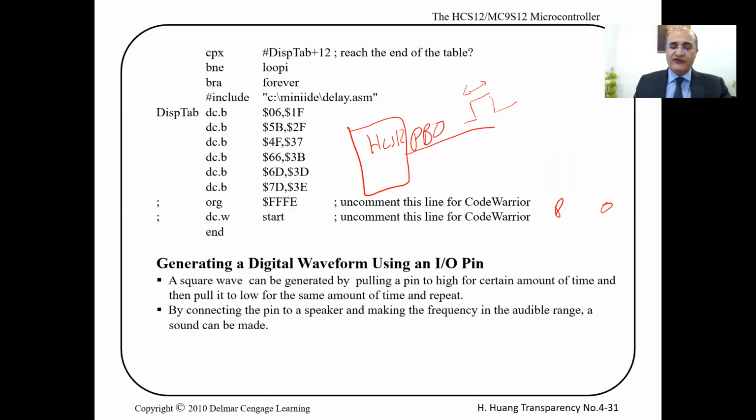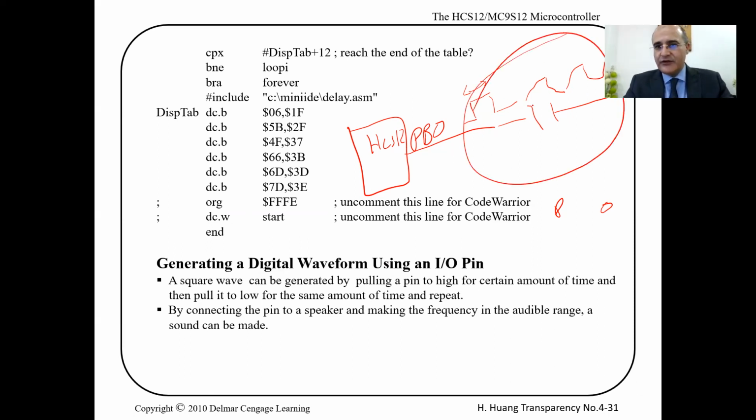Well, if you want, for example, a sawtooth waveform or a sinusoidal signal waveform, well, this is your job to add the interfaces, right? For example, if you add a capacitor after this pin, the capacitor will take time to charge, right? When you have a zero, it will drop faster, rise, drop, rise, drop, right? You can add some filters, and you can reshape the waveform you get.